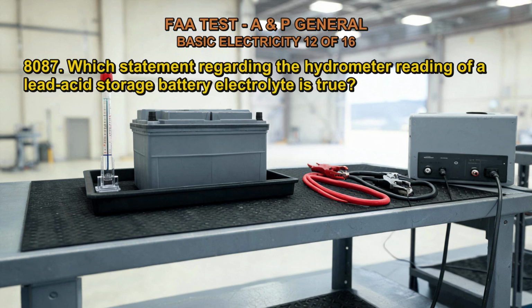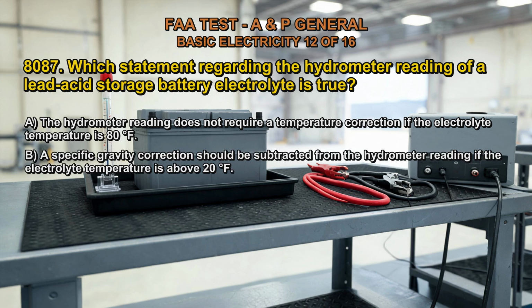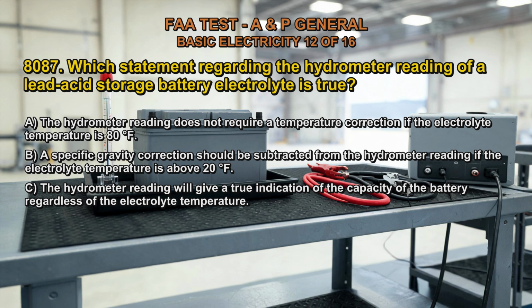Q8087. Which statement regarding the hydrometer reading of a lead-acid storage battery electrolyte is true? A. The hydrometer reading does not require a temperature correction if the electrolyte temperature is 80 degrees Fahrenheit. B. A specific gravity correction should be subtracted from the hydrometer reading if the electrolyte temperature is above 20 degrees Fahrenheit. C. The hydrometer reading will give a true indication of the capacity of the battery regardless of the electrolyte temperature. The correct answer is A.